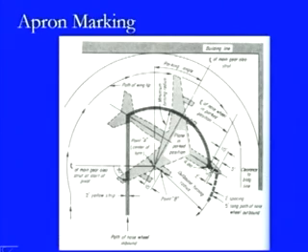So, this is how it will happen, and then once it is being loaded, it is to be taken out. Now, this will be moving along this particular path. So, we have the outbound turning radius and we have the inbound turning radius, and the minimum radius with which it will be working, that is this value. So, likewise everything is defined for this sort of an operation, and some clearance with respect to the building line is also being provided, so that there is no damage to the wings of the aircraft while it is taking a turn and moving away from the building.